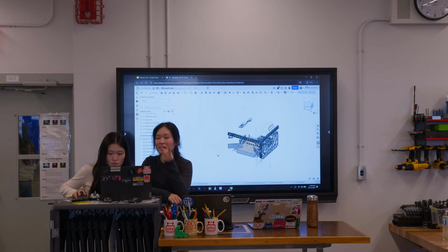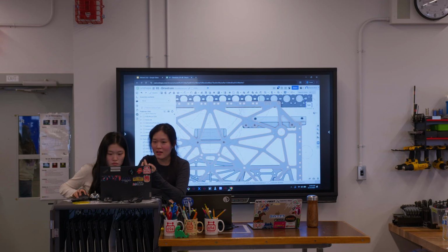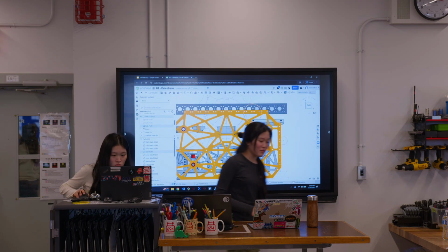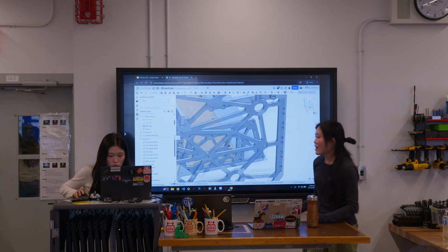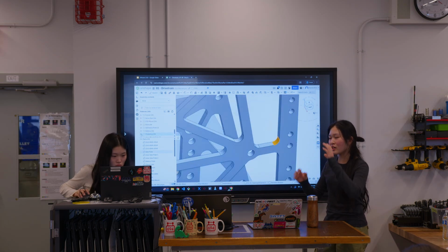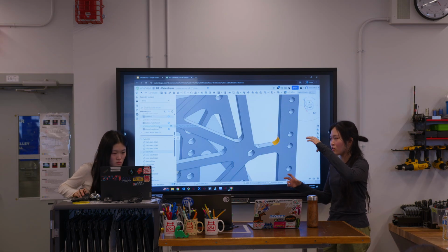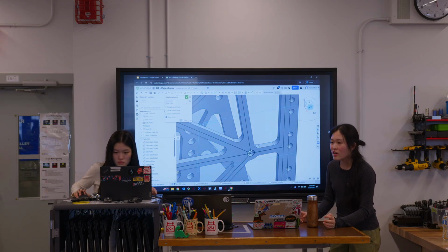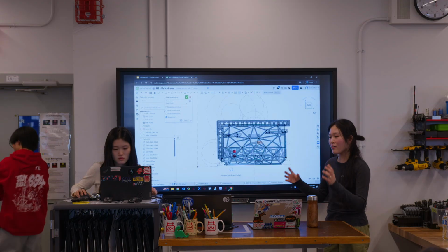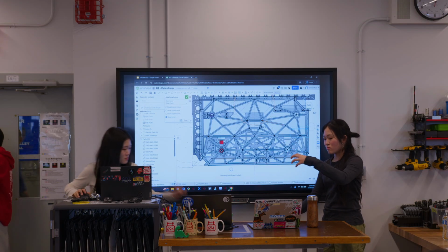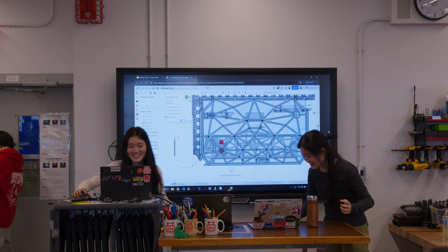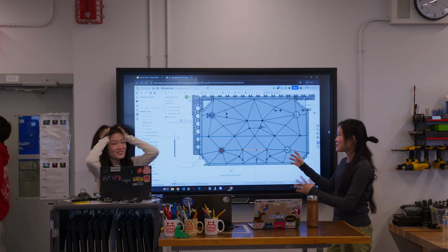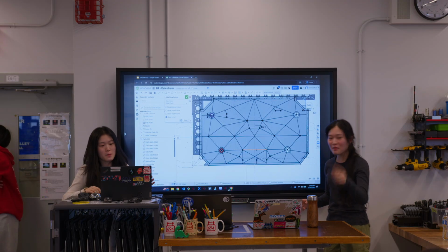The second method is kind of uncommon, but sometimes manual pocketing is really useful. What I realized when I was designing the telescoping arm is that it basically has a pocketing with lots of triangles that are basically uniform. And sometimes the location of the pocket really matters. For instance, in the telescoping arm, the bearings in the interstage must slide not on the pocket, so the location of the pocket really matters. Sometimes you want to manually pocket.